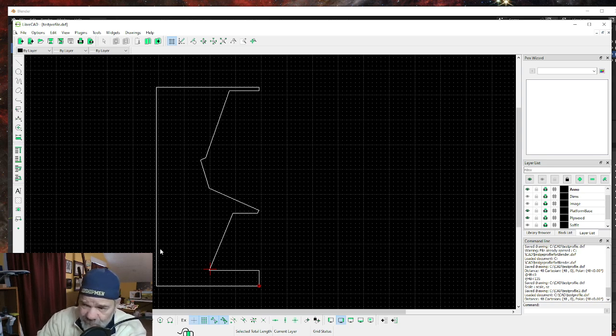So when I measured this, it said 48 inches. If I bring this into Blender, it's going to think 48 meters. If you're in the metric world, you just work those metric measurements like you normally would, and when you bring those into Blender, they're going to be in metric.